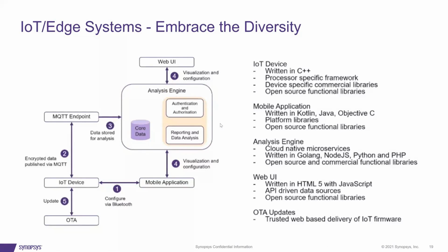How are they talking to each other? The device is talking via Zigbee or Bluetooth or Wi-Fi. If it's in a car, maybe it's actually talking over CAN bus. And then you've got some of the higher level application layers of MQTT. You've got HTTP. You need to understand each of those interfaces and the protocols and really fully test the robustness of each of those segments, which you can't do unless you identify them first and see where all of those attack vectors really are by doing a really complete threat model.